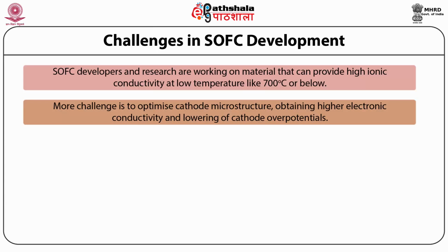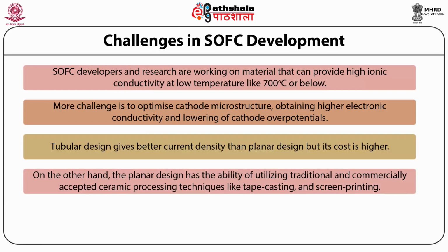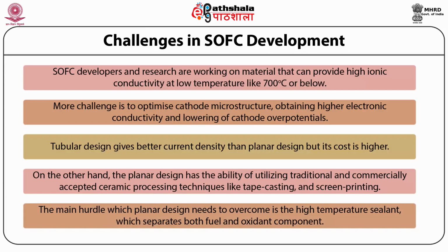Both tubular and planar designs have their advantages and disadvantages. Tubular design gives better current density than planar design, but its cost is higher. On the other hand, the planar design has the advantage of utilizing traditional and commercially accepted ceramic processing techniques like tape casting and screen printing. The main hurdle which planar design needs to overcome is the higher temperature sealant, which separates both fuel and oxidant components.